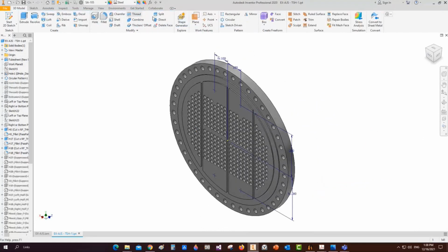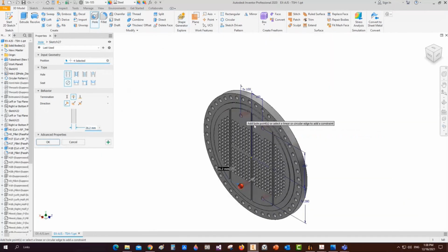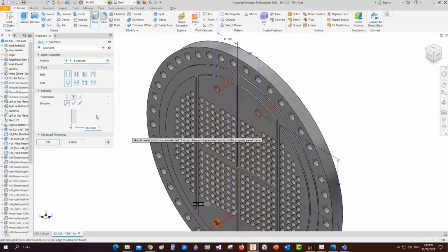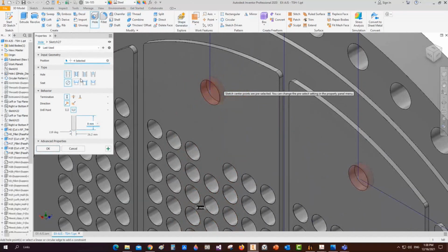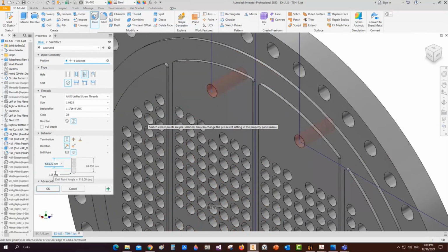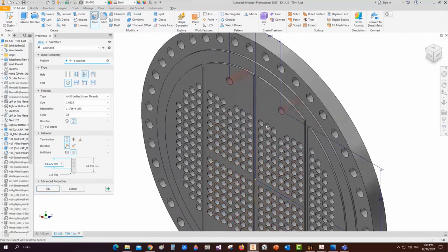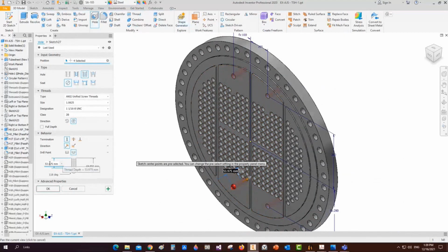We can use them now to make a hole. So from here you can select the hole feature, which is that one, and automatically you can figure that the hole configuration is selected for the 4 points. And from here you can select if you would like to make it with a distance, hole with a distance like that, and if you would like to add a thread on it, you can define the thread length. Now you have full control on the hole shape that you would like to generate.